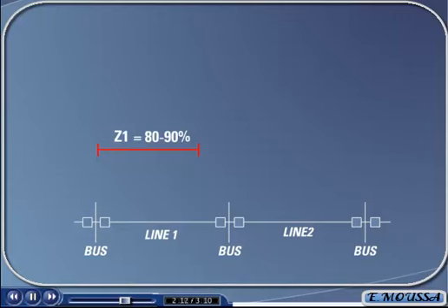If the fault was transient in nature, the first occurrence of tripping the line would have removed the fault and transmission of power would resume. If the fault that occurred was a permanent fault and reappeared after the reclosing, but was not located in the new shortened Zone 1 protected area, the relay would not pick this up for a second time in Zone 1 and not trip to try to clear the fault.